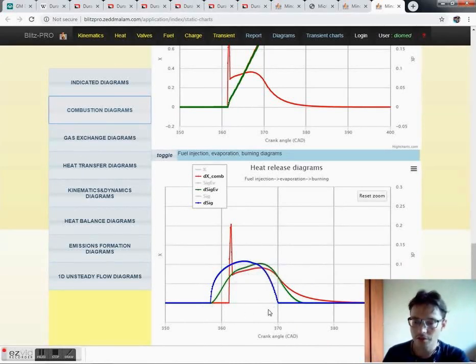And it is injected so fast because of high injection pressure. And also the droplets are very small because of high injection pressure, and that's why they evaporate very fast. Both make the conditions for the fast kinetic combustion at the first stage of the fuel vapor which was made during the ignition delay.